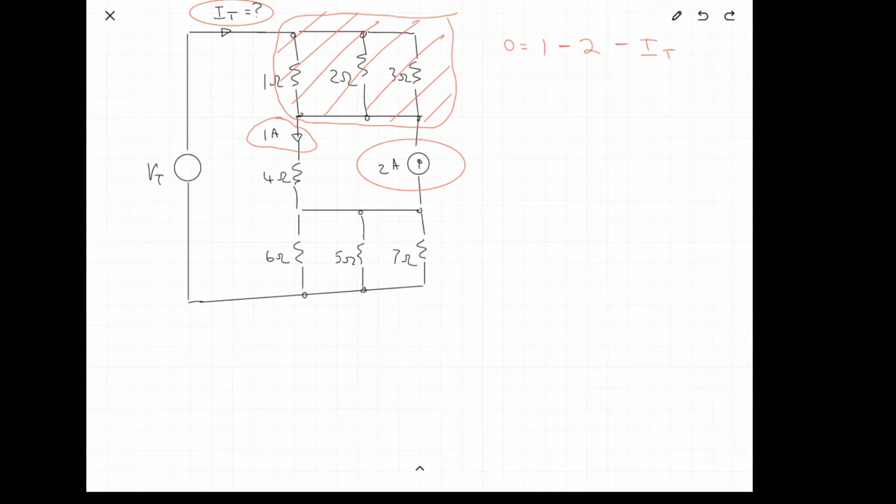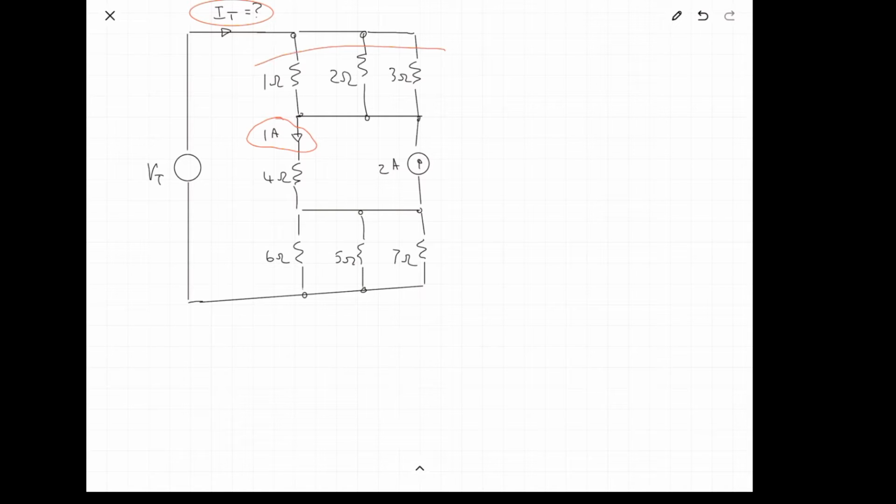just undo all of my working here. Say we didn't do that. What we would do then, another approach, would be to combine those 3 resistors. So 1 on 1 plus 1 on 2 plus 1 on 3. Invert that. That gives us a new resistance. Now that resistance happens to be 546 milliohms. Is 546 times 10 to the minus 3 ohms.